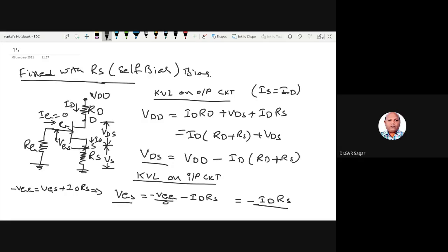So when the drain current here is slightly increased, the voltage drop across RS increases. We have already studied that when more current flows in the channel, the temperature rises. That current flowing through the source resistance creates a voltage drop, right? So across RS the voltage drop is increased.